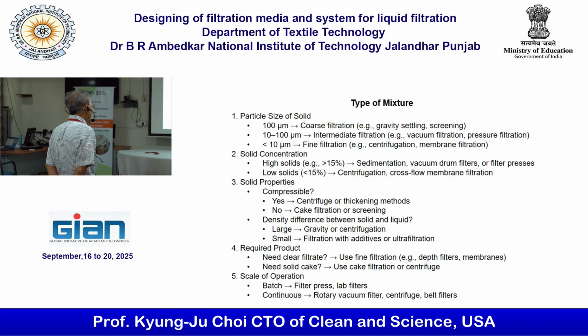A little bit bigger, vacuum filtration, pressure or settling is good enough. Solid concentration: high solid concentration, certainly sedimentation, vacuum drum filter process, filter press, and low, certainly centrifugation and